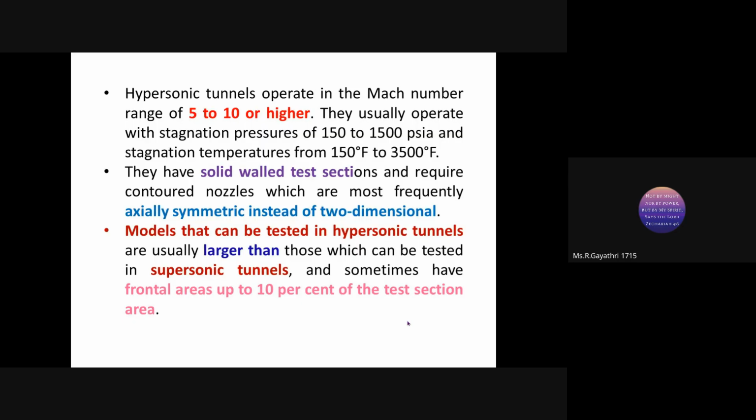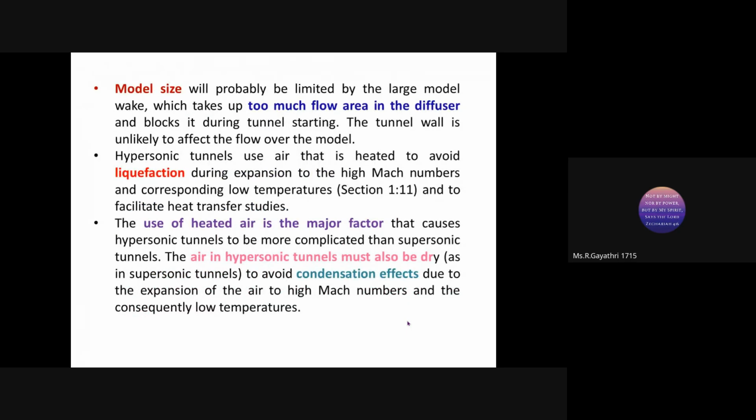And the sizing of the model should be larger than that of a supersonic tunnel model. The model frontal areas can be kept up to 10% of the test section area. And the model size can be limited by the large model weight.